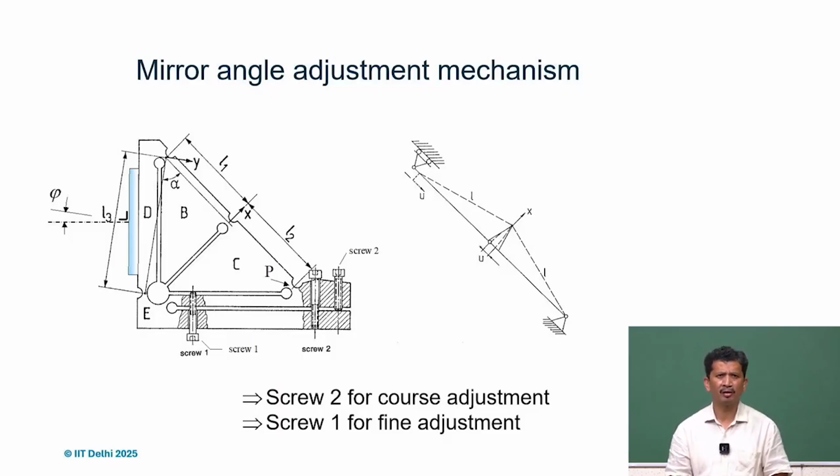Of course, if we are looking for a very targeted application, maybe an arc second or arc minute kind of adjustment or resolution, these kinds of elements are very important. And yes, here we are talking about adjustment with the screws. It's just to illustrate, but if it has to be done in a very dynamic way and at very high speed, then of course the screw can be replaced with some kind of actuators, piezo actuators, or other linear actuators, depending on the application and the payload.